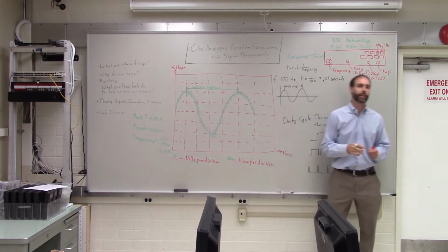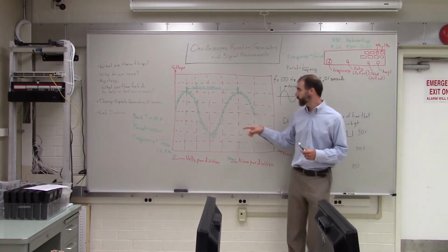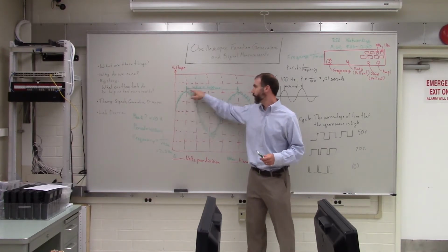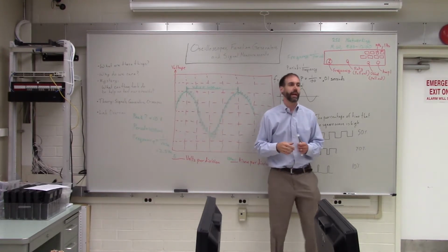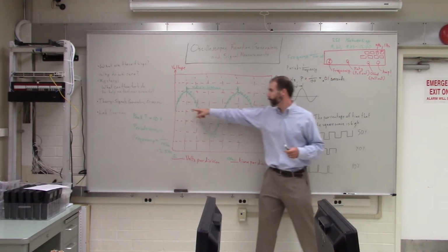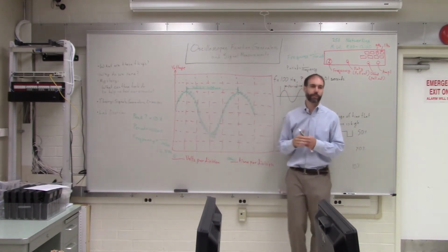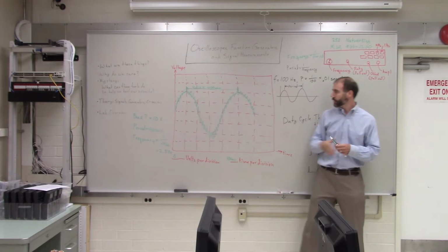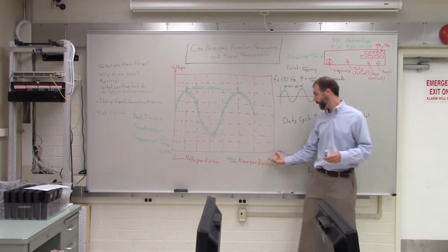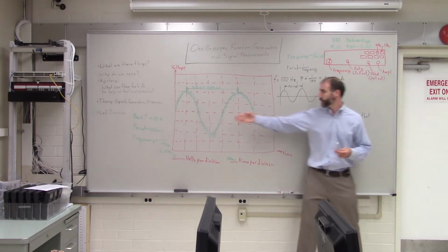But when you ask the computer to make the frequency measurement for you, it might look at this and say, oh, this has got a lot of frequency there, I'll measure that frequency. And so it'll give you a frequency measurement, but it'll be the frequency of the noise rather than the signal you actually care about. If you didn't look at this graph and understand what was going on, you would just have that one number and you'd have to trust that. So it's important to look at this.